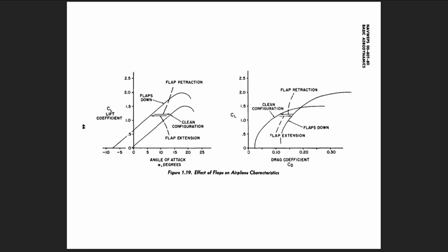3. The retraction of flaps requires an increase in angle of attack to maintain the same lift coefficient. Thus, if airplane acceleration is low through the flap retraction speed range, angle of attack must be increased to prevent the airplane from sinking. This situation is typical after takeoff when gross weight, density altitude, and temperature are high. However, some aircraft have such high acceleration through the flap retraction speed that the rapid gain in airspeed requires much less noticeable attitude change. When the flaps are lowered for landing, essentially the same items must be considered.